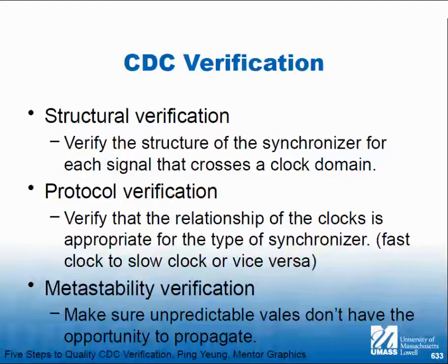So here's the math. Every flip-flop in the design was triplicated, and the output of the flip-flop was measured based on best 2 out of 3. So every flip-flop, this is the factor of 3, the 50 to 150, was really 3 flip-flops.